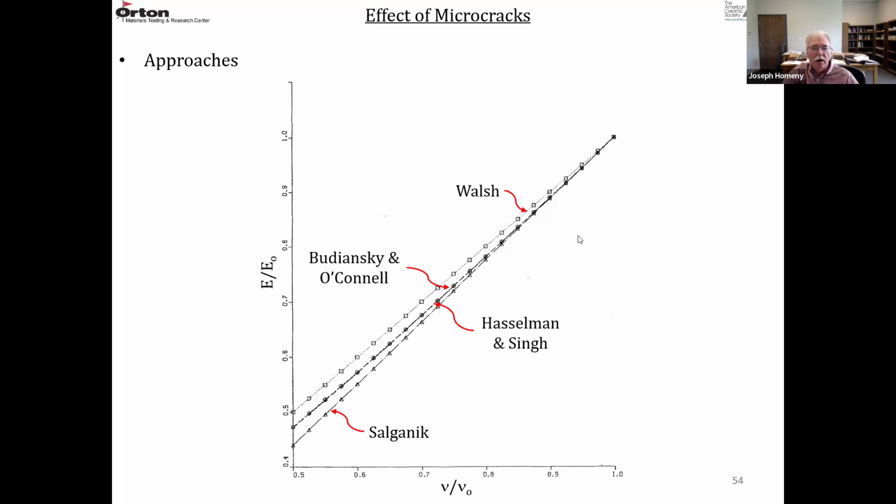I don't think anybody has modeled the relationship between porosity and microcracks in one model, but you can calculate the average crack length. You can measure the average pore size. Porosity, when pores are stressed, especially if they're not round pores, can create more microcracks. Thermal expansion mismatches can create microcracks. Pores can create microcracks. But I don't know of any models that include both pores and microcracks.